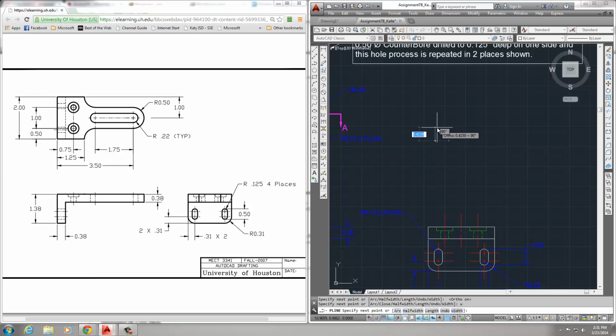Let's create the width. Down at the bottom, you have W for width. What I'm doing is changing the width to make it thicker, right? So why don't we go a little bit thicker, like 0.06. That's the beginning width, and the ending width should be the same, so it's the same thickness of line. So I'm going here, going over here, going down, going over, and I need the little kicker to put the arrows on.